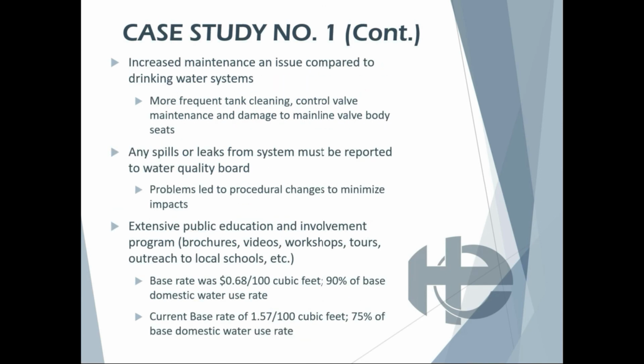There are some increased maintenance issues compared to drinking water systems. The tanks that they use for storage do have to be cleaned a little more frequently. Your control valves, valve body seats do require a little bit more maintenance than just simply a drinking water system. Any leaks or spills from the system have to be reported to the Water Quality Board. It is still considered a wastewater, not your true potable drinking water, so any kind of a spill is essentially still considered a spill of wastewater. The system has developed a very extensive public education involvement program, all kinds of brochures, videos, workshops, tours, and so forth, to keep the public informed about the project.